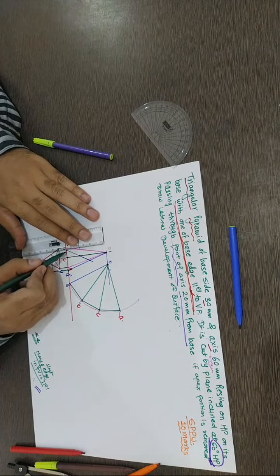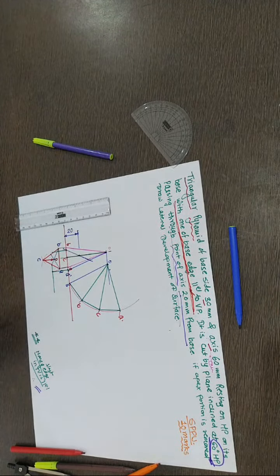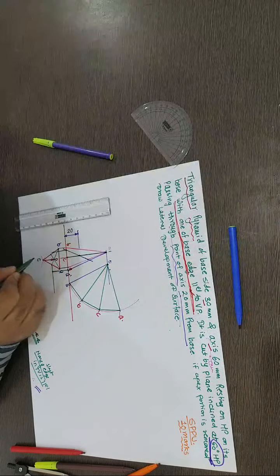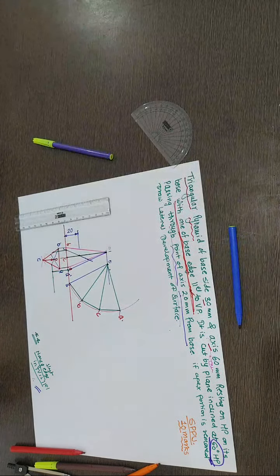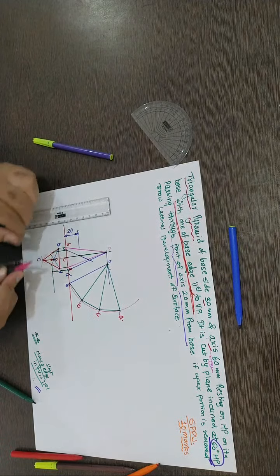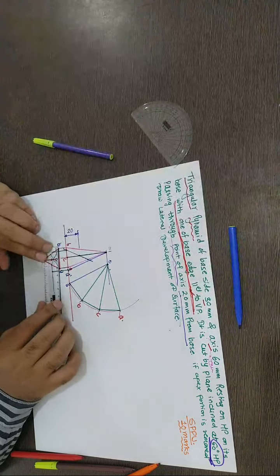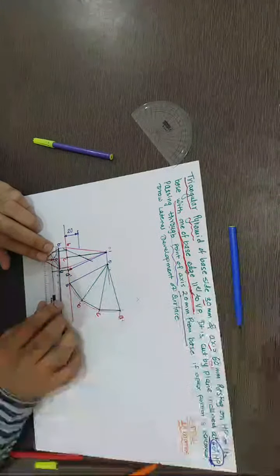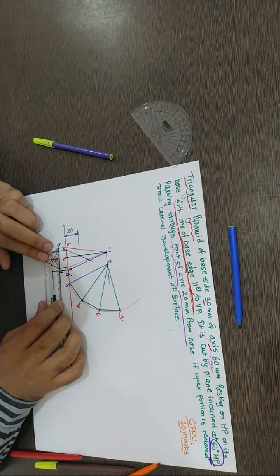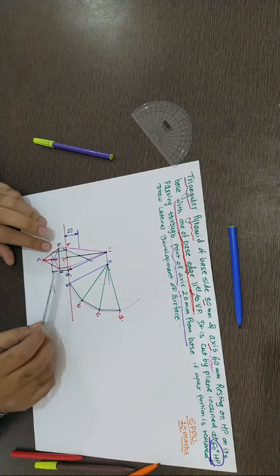Project this point of base intersection in the top view. It cuts two points. One is here, A, another is this BC. So same logic. Take a distance in the compass. From B, take this distance. As it is very small, I'll use only the scale right now. So it is around 5 to 6 mm, approximately the same, from B towards A.